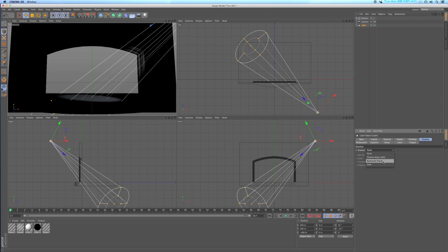We tend to use that when we're rendering something that's outdoors, because the shadows outdoors tend to be much harder. Shadows in the theater tend to be softer. That's just my own opinion. So it renders faster, so I'm going to use the soft shadows. The other thing I tend to always want to change, the density of the shadow. Shadows are never, in my opinion, 100% ever. So I'm going to change that to 75%.